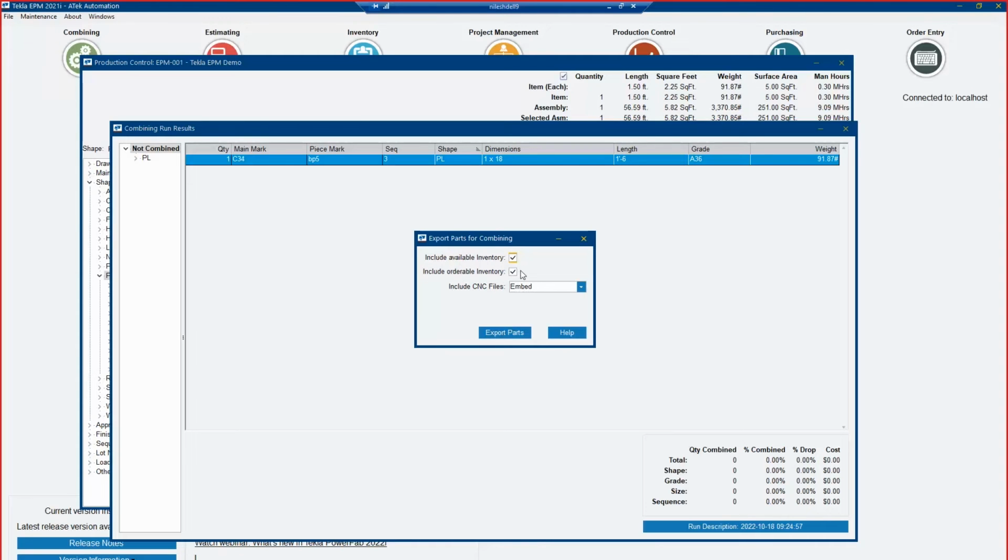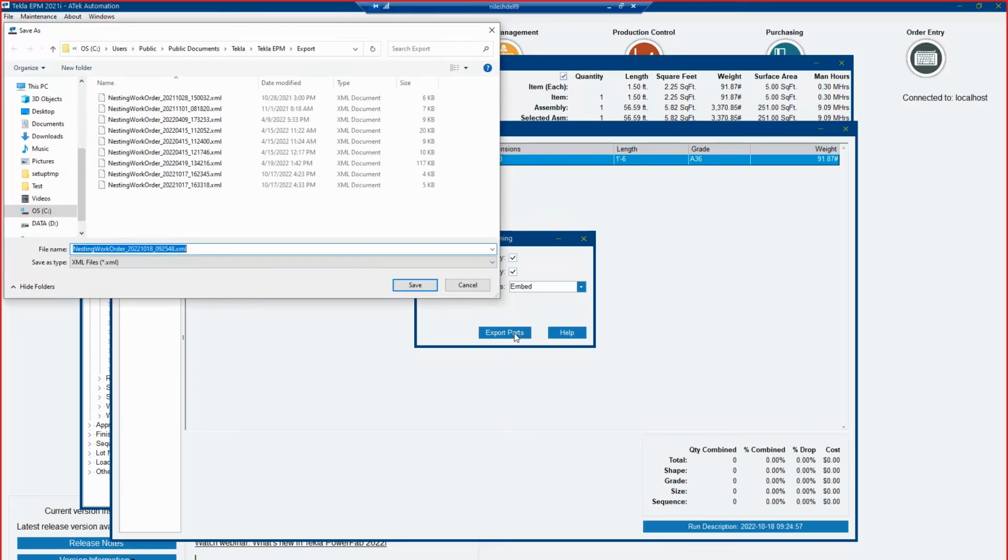Say sometime you don't have a part or a plate in stock, so you can say, okay, this is my orderable size. Say you ordered a 1-inch 8x8 or whatever you have specified in Tekla. They will give us the surface size you ordered for 1 inch. Then we click Export Parts, and that will export everything into the file. Now choose the directory on your network where you want exported files to be sent, and remember this location for later steps.